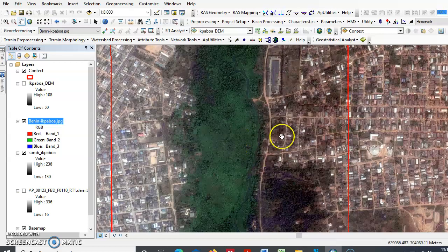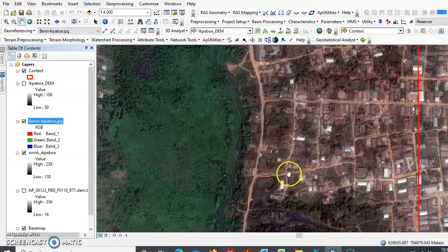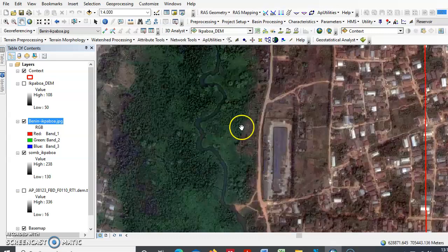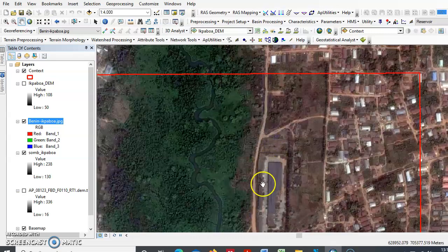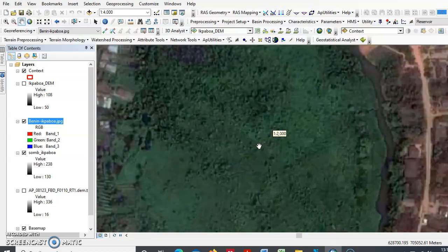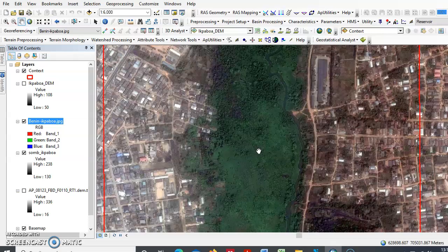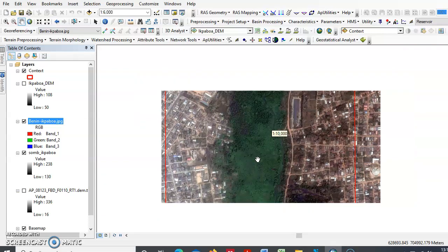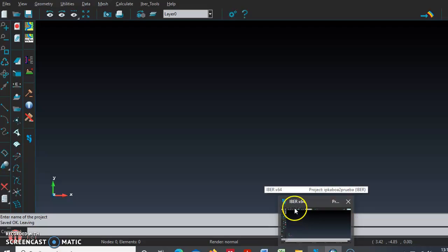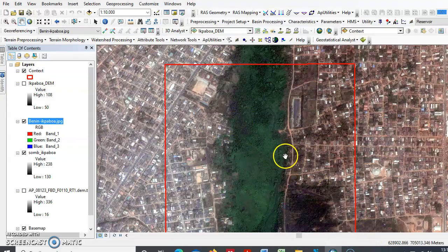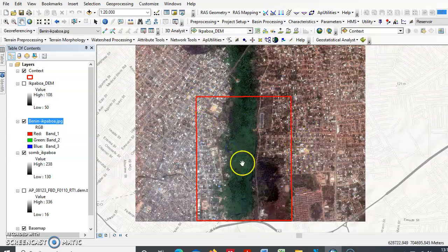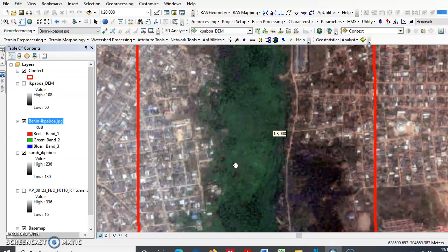Okay. So, as you can see, you need an orthophotography that is at least, well, I don't know, but maybe 5 meters of resolution is good. It depends on the size of your working area, no? Because more resolution and a bigger area will work worse in your Iber. So for a place like this square, this resolution of 1 meter is enough, I think.